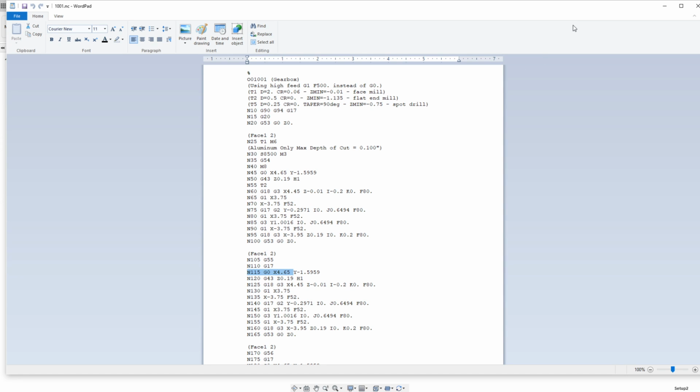And it's not something that we can simulate because we don't know necessarily how those work offsets were placed in the machine. So you could have, let's say you have 4 work offsets. The first 2 work offsets could be spaced 3 inches apart. The next 2 could be 4 inches apart. The next 2 could be 1 inch apart. We don't necessarily know that from the CAM system. All we can say is that, yeah, we're going to output operations to each offset. It's up to you to make sure that they're spaced the way that you want them to be.